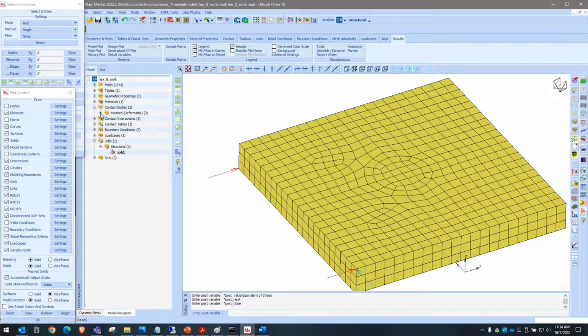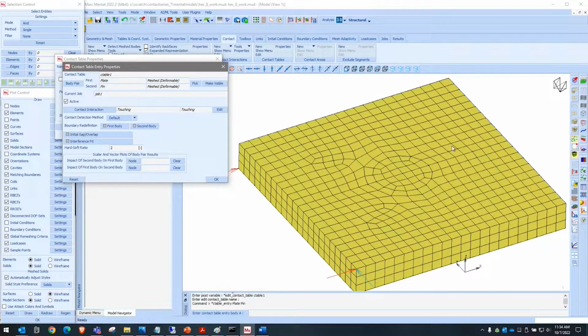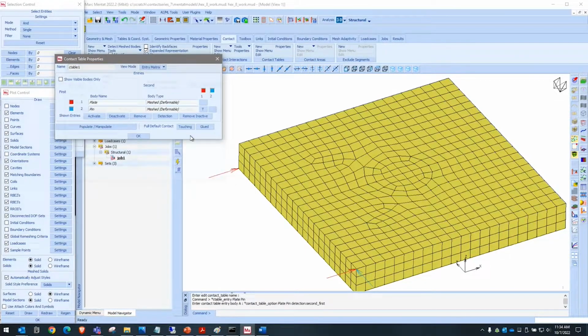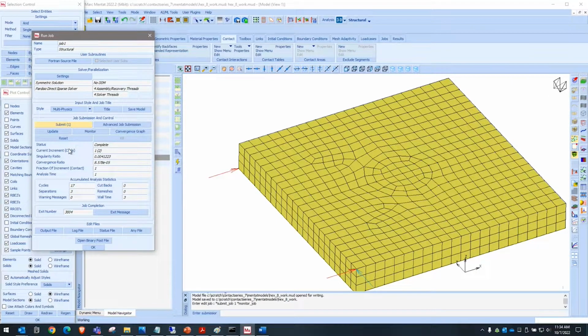So before I do the interference fit and stress free and so on, let's start with my contact table. Let's swap the contact around. I want to make contact from the inside to the outside. For a lot of the settings, it'll make more sense if we start adding smooth surfaces. It doesn't matter too much what direction we're doing, so let's just do this at least. So I fix second to first, so the pin will make contact to the plate. We rerun the analysis and there will probably be a slight change in the answer, but not much.